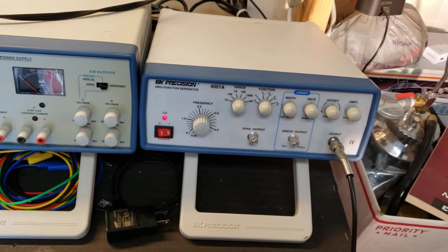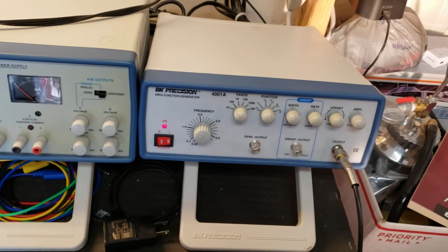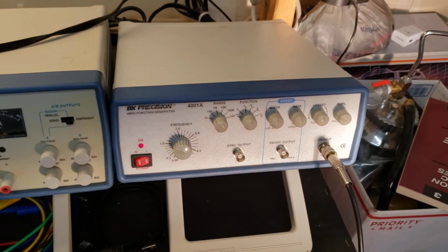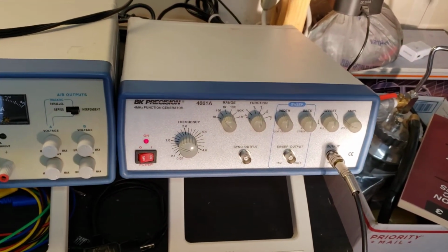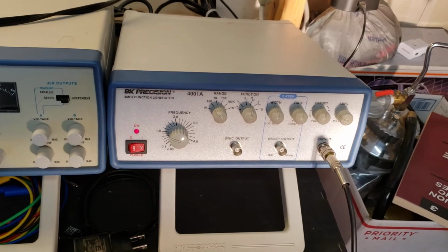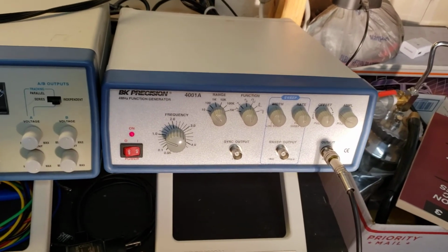I've never tried the other waveforms on it. I'm sure it would work as well, but what I found on this vehicle, you would think it produces triangle or sine wave, but what it's producing, because I think there's a bias voltage, is some kind of square wave, which we picked up on the oscilloscope.